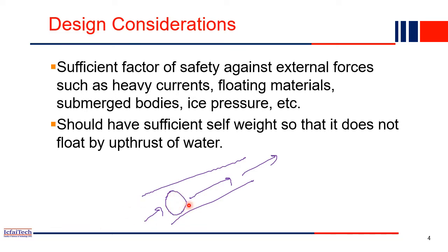That's why it will be subjected to very high extreme water current, right? Similarly, floating objects, even if floating soil objects are passing, will also hit the intake structure. Similarly, during a flood the water level will increase, and ultimately the pressure will also increase. And maybe if the river is nearby a polar region, then ice may also come during the winter time, so our intake structure must be able to take the ice pressure as well. So that is our primary design consideration while designing this RCC structure.